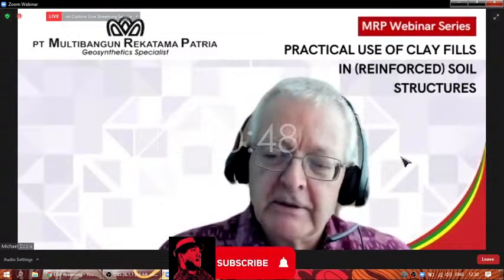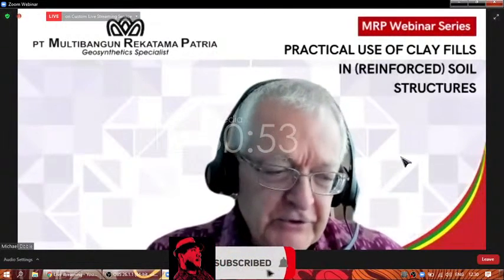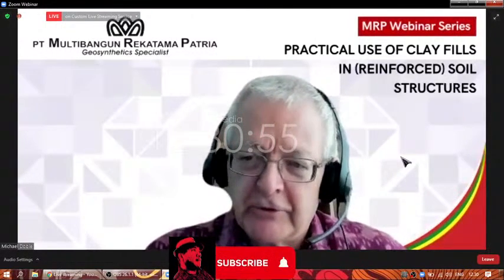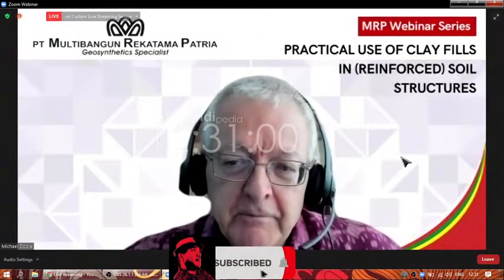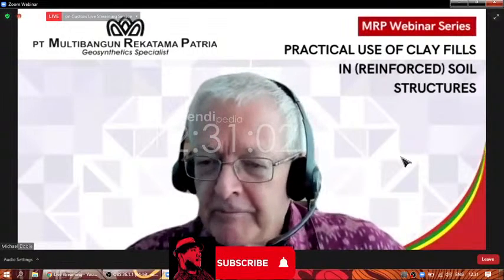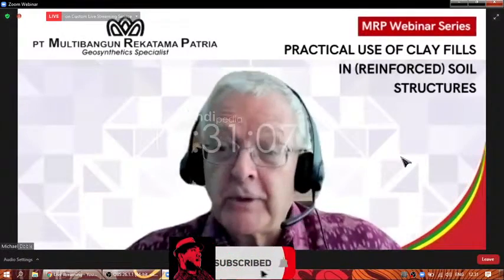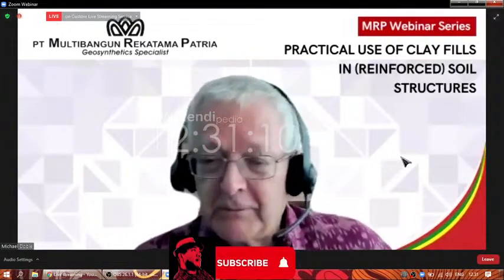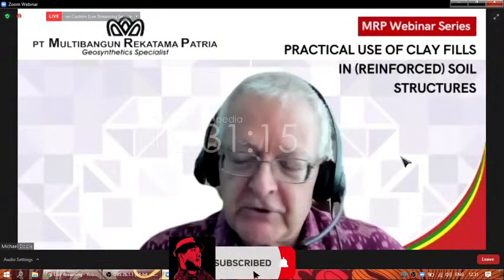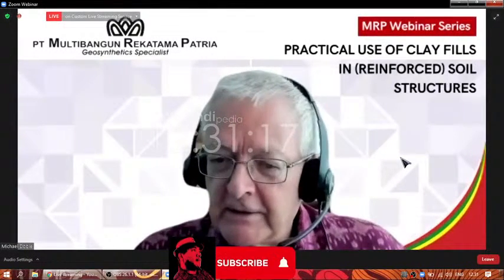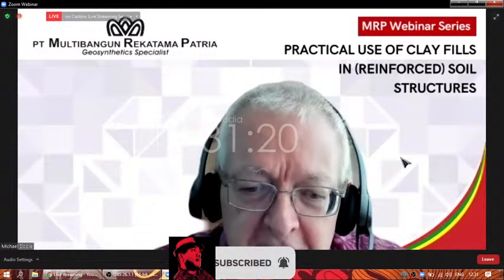But again, it's an engineering situation, so you need to look very carefully if you want to consider using metallic reinforcement in a clay fill. But I think you'll find that most people who develop those systems will require that they are used with granular fills. There's also a question of interaction between metallic strips and a clay fill. Will it be as effective as interaction between metallic strips and the granular fill? So there are other considerations in that particular answer.